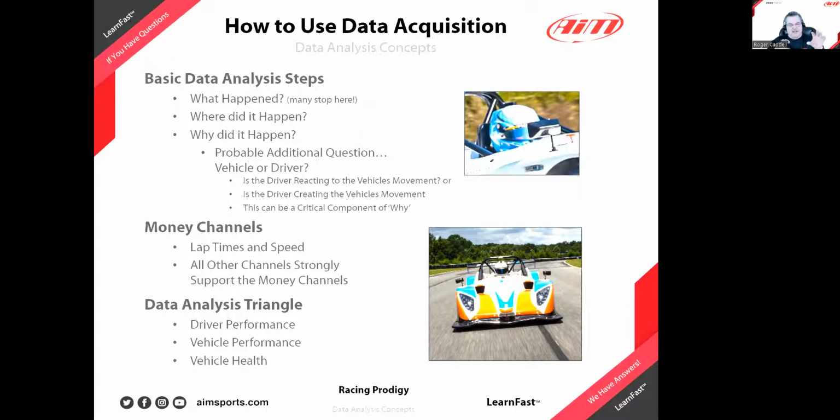So all of those other channels, and I will show you how I do it here in just a moment, but I open up a basic speed trace to begin with. Speed trace 2 of your laps, or your competitor's lap, or last session versus this session lap on top of each other, see where the difference is, and then start throwing these other channels at it to understand why you are faster or slower. The money channels, always be trying to improve the money channels.